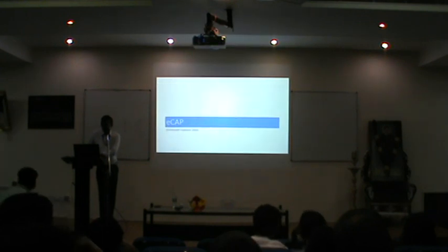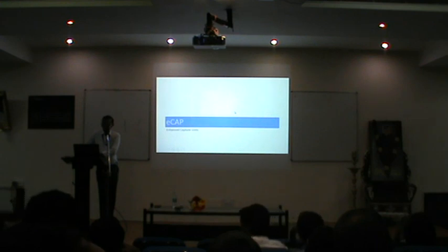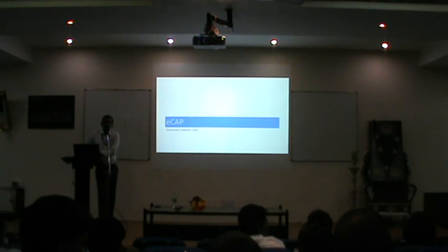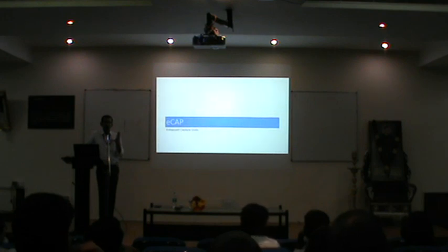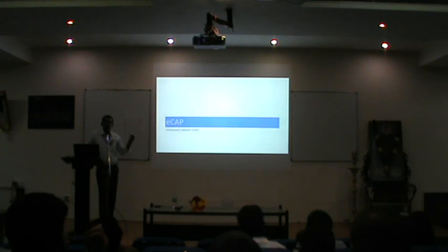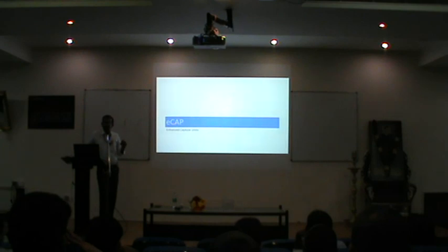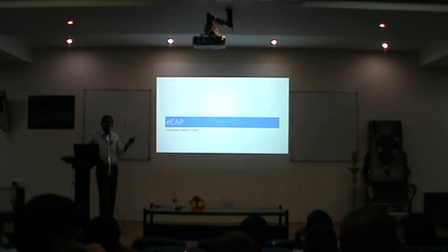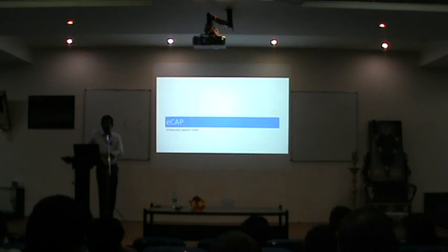Now you have something called eCapture modules. The eCapture modules functionality is what you will be using to sense the speed or perhaps to determine the direction of rotation. First thing we saw is control. Converter, motor control setup is there. Your converter needs to be controlled, provided with switching pulses. How will that be done? Using PWM signals. And this particular PWM generation is based on environmental parameters. So to sense the environmental parameters, we saw how to utilize the ADC. The other environmental parameter, that is your speed, can be sensed by using these capture modules.